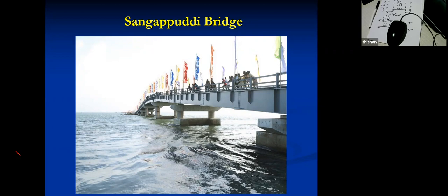There was one bridge built by German aid in 1962, and I found that this particular bridge is fully galvanized. Earlier we used to have bridges that we painted with bitumen, and those bridges lasted very long times, because bitumen could give near perfect protection against corrosion.